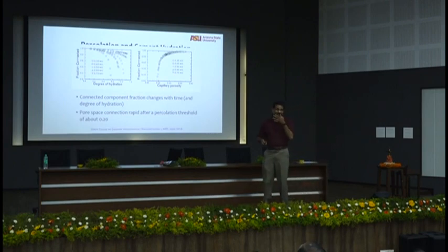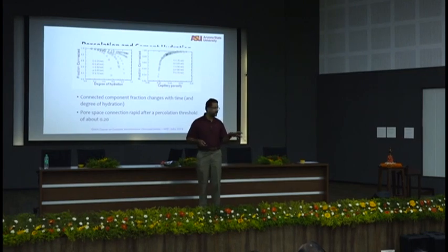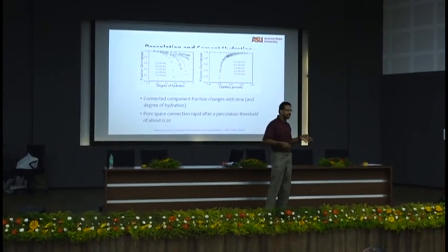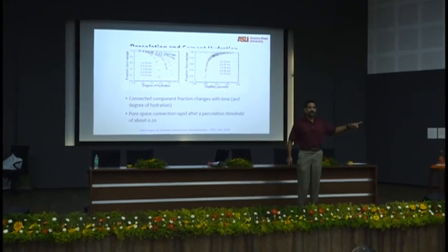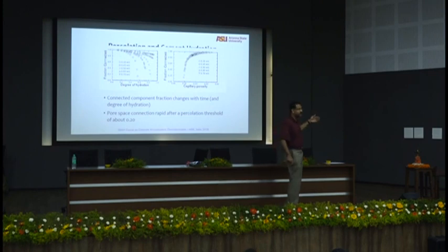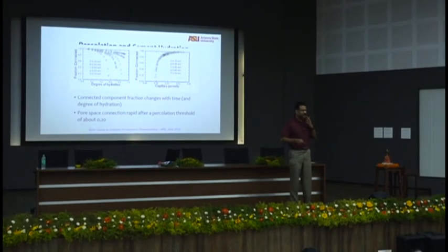and that is why I keep emphasizing the point over the last 3 days that concrete is a material that has to be designed, not proportioned. We do mixture proportioning, we don't do mixture design. What is your proportioning? How much do I need to satisfy what somebody else wrote in a code? That is proportioning, right? Your cement content has to be this much, your aggregate content has to be this much, you still use all the charts.